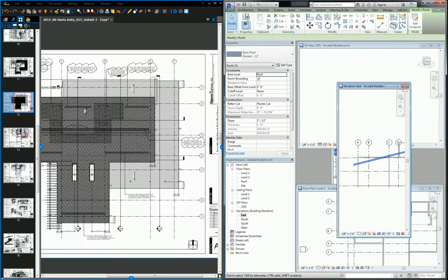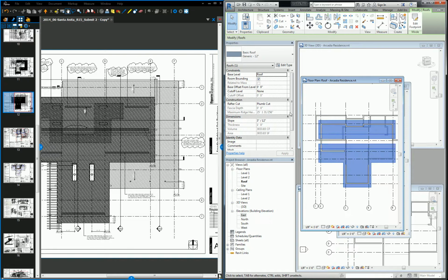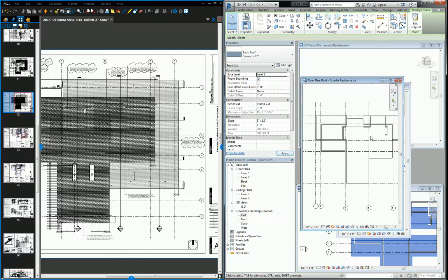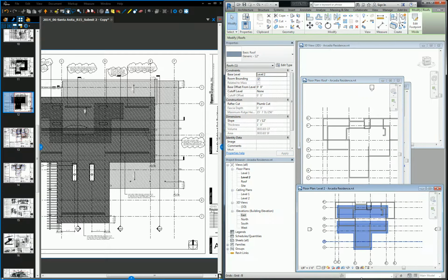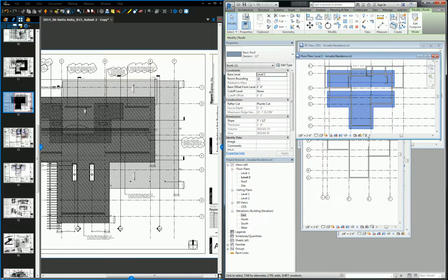So there are a number of things that you guys will need to troubleshoot during this process. One of them is, what if I drew it in the wrong view? Which is what you're talking about, Nafi. If you drew it in the wrong view, the roof itself might look similar. Let's say I was viewing the second floor when I drew it. Hang on, let me pull it up. So it looks like that on the second floor.